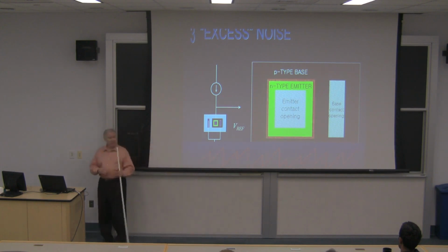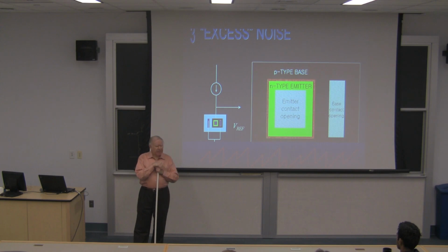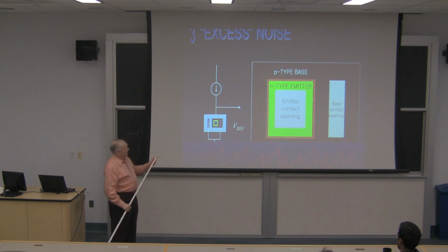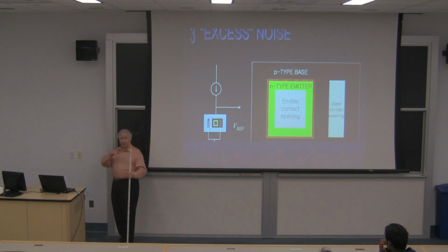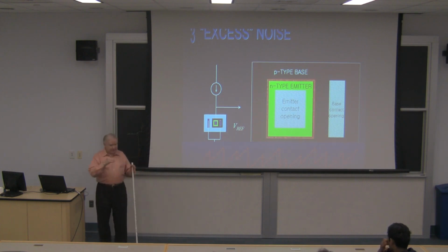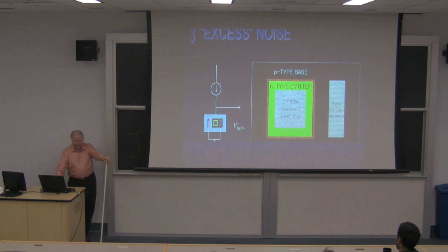So, do you know how that's overcome today? I don't know if this is something that's included in your curriculum. It's a little bit out of date, as I say. Except in high-performance converter products, we tend not to use breakdowns as references. But I had the idea many years ago, I can't remember the years, between 70 and 72, of burying the junction so that it was below the surface, because much of this is due to surface effects where the etching is not quite perfect, and by pushing the junction below the surface, we can end up with a breakdown that doesn't suffer so much from these random variations. And a buried zener is very much quieter than a surface one of this sort. But you probably won't encounter that in the kind of circuits you design. You're probably using a band gap reference in many cases. Noise in the band gaps is something that we may have time to talk about. I doubt it today, but we'll see.